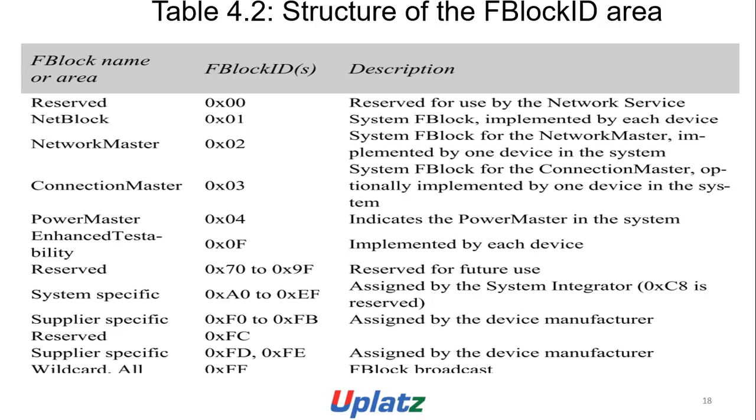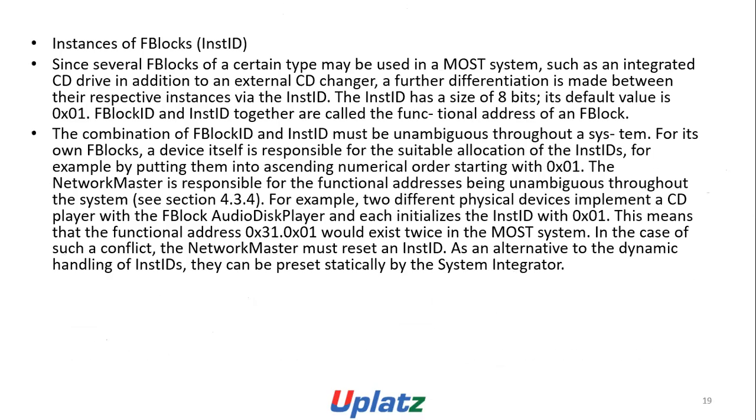Supplier specific 0xF0 to 0xFB assigned by the device manufacturer. Reserved 0xFC. Supplier specific 0xFD to 0xFE assigned by the device manufacturer. Wildcard all 0xFF block broadcast. Instance of FBlocks: InstID.